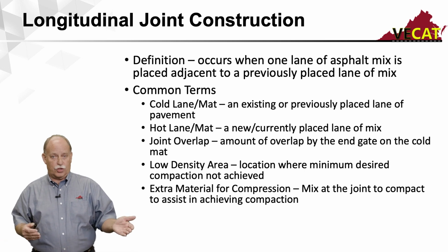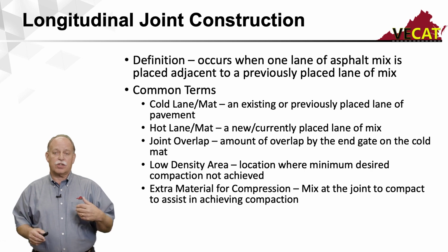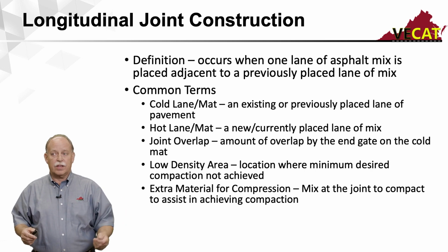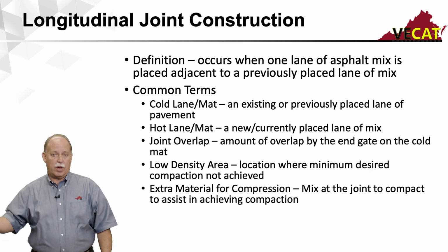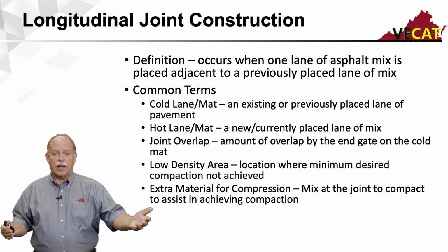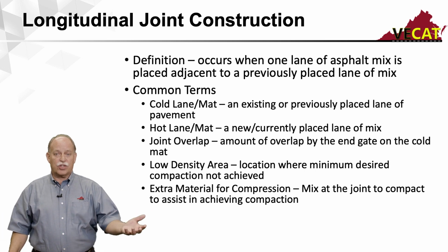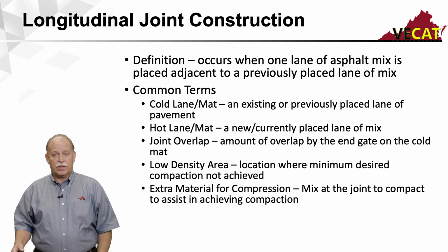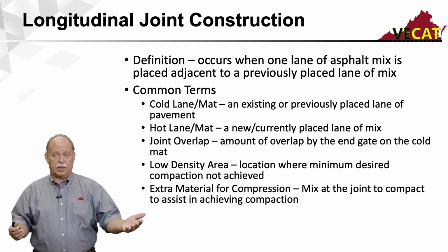There are some common terms that you'll hear as you're going through the paving operations. You'll hear things such as the cold lane or the cold mat, that's the existing or previously placed lane in your pavement. It was placed, let's say, yesterday, and then you're coming back the next day, so that's the cold lane or the cold mat. Then there's the hot lane or the hot mat. That's the lane that you're placing today or that you're placing now. So that's the new one currently being placed, and it's going up against the cold lane typically.